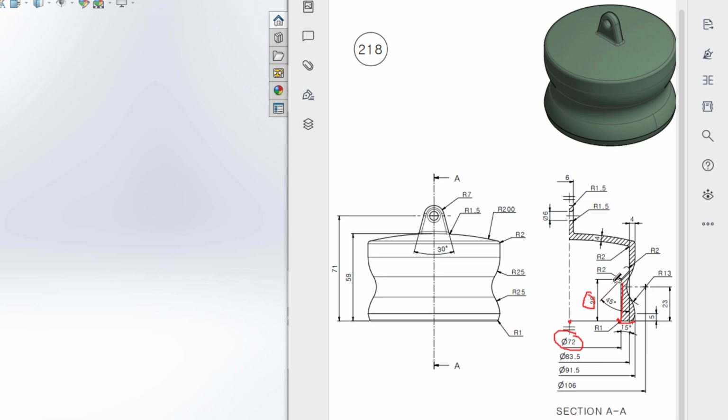As I have previously drawn this circle of 200 radius, we need to draw another offset circular profile of 4 distance. We'll draw this offset profile distance. After that, we'll draw this vertical line, and this vertical line has a distance of 183.5 unit divided by 2 from here.